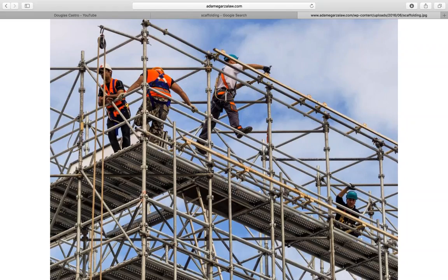so different types of energy that we have to lock out, tag out, right? Mechanical energy, anything in movement. Could be auger bits, could be blades, could be pistons, anything that could be in movement. Also pneumatic, basically air powered, hydraulic powered, electrical, chemical, thermal, hot or cold, either way. Radioactive, it could be gravitational, where, like I said, a dump truck bed or the top of a press that's stuck in the up position, maybe they got jammed. And then any type of stored energy, like capacitors. Anybody who's familiar with struts, like on a vehicle?